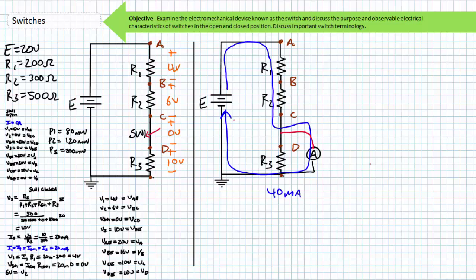If this was a current limited power supply, and we dropped the resistance too low, we might enter constant current mode where the power supply simply refuses to supply current in excess of some preset maximum by dropping its output voltage. If this source was protected by a circuit breaker or fuse in series with this circuit, and the shorted component caused current draw in excess of the breaker's or the fuse's rated current, the breaker would open or the fuse would pop, effectively turning off the whole circuit and preventing potential damage.